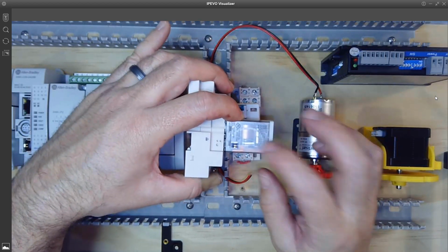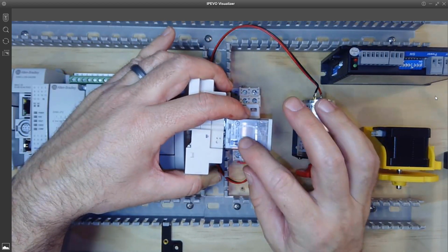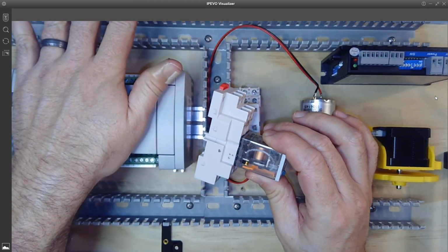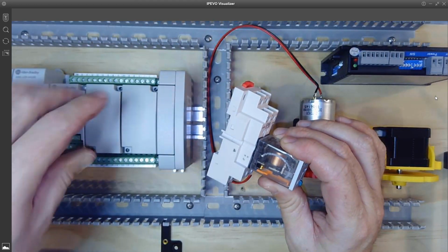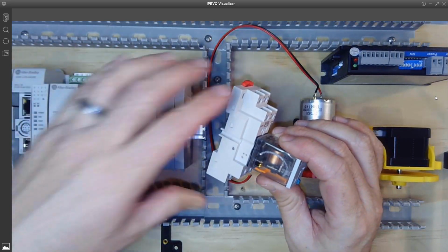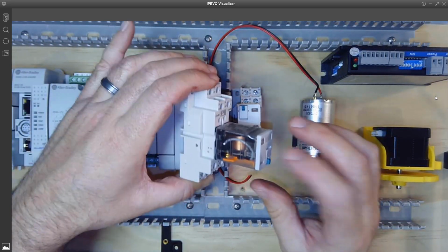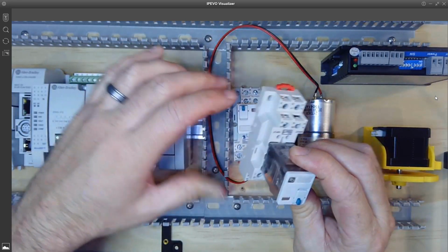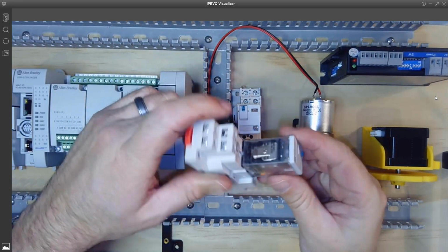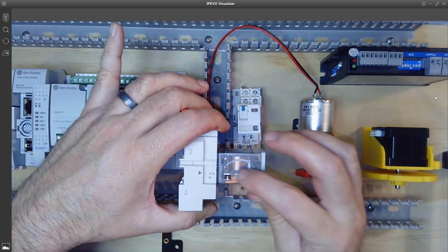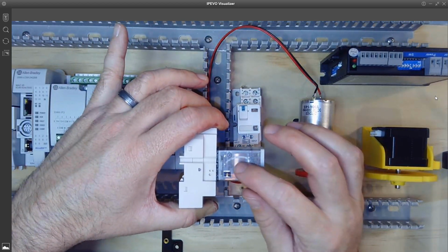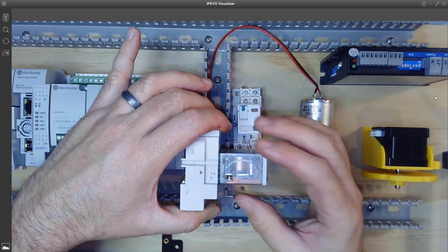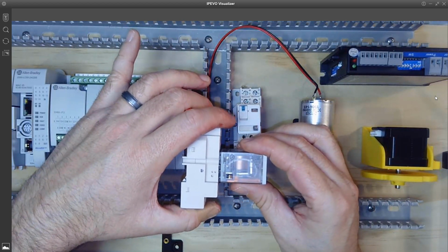And we do that so that we are wearing out the contacts of this relay external to the PLC rather than internal to the PLC transistors. And the transistors in the PLC are good for about an amp, whereas this I think is rated for 8 to 10 amps. So you're going to use that, but if you also remember back to MEC232, what happens when you have an electromagnet with a magnetic field around it and you turn off the current that's energizing that field?